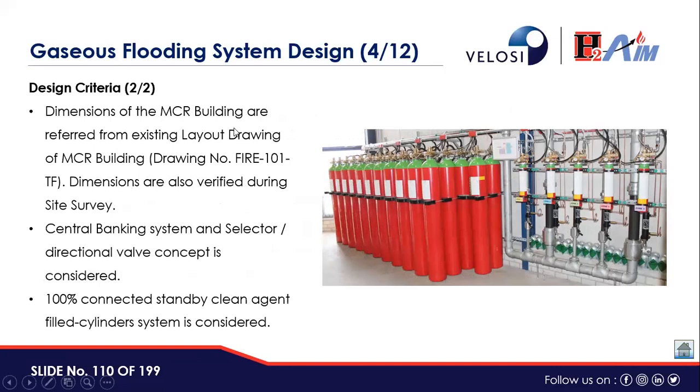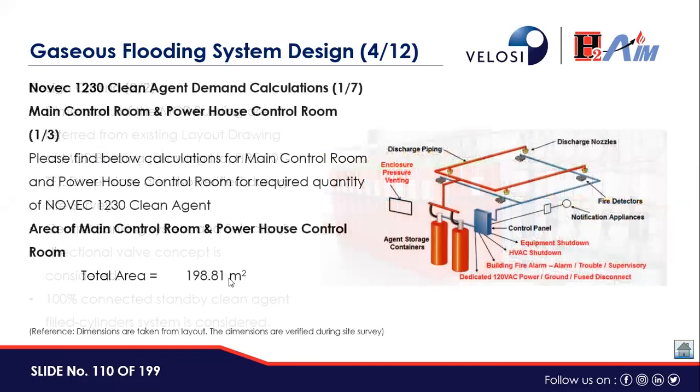Dimensions of the MCI building are referred from the existing layout drawing, and the dimensions are also verified during the site survey. Central banking system and selected directional valve concept is considered. 100% connected standby clean agent filled cylinder system is also considered.